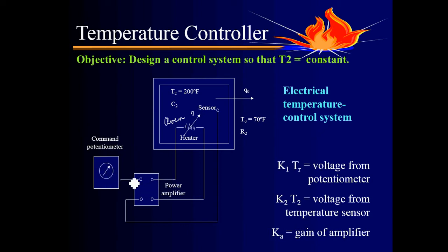Set the temperature. This little box is going to sense the voltage that comes from the thermocouple that measures the temperature. Inside this box, it is going to say to the control system, hey, turn the element on or turn it off, depending on whether you reach 350 degrees or not, and turn it off to try to maintain this.